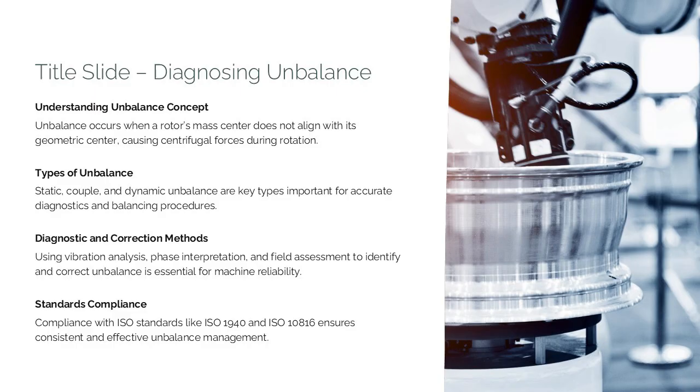The material is based on vibration analysis knowledge, framed to support predictive maintenance programs and reliability engineering initiatives. Within this context, unbalance is defined as a condition where the rotor's mass center does not coincide with its geometric center, producing a centrifugal force when spinning. This force leads to elevated vibration, reduced machine efficiency, and accelerated wear.